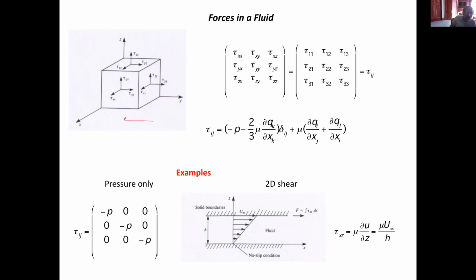So I'm looking at this cube, okay? And in mechanics, you try to have this Cartesian coordinate system, and I'm trying to look at what kind of forces can act on that fluid. So we had looked at body forces, which is like rho g, and surface forces. Now, this little cube summarizes the surface forces. So, for example, on this side of the cube, which is facing the plus x direction, there could be a pressure.